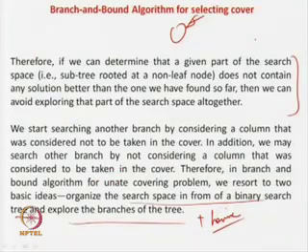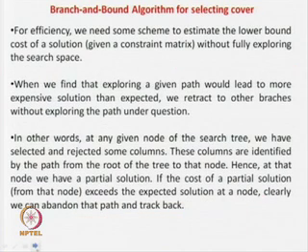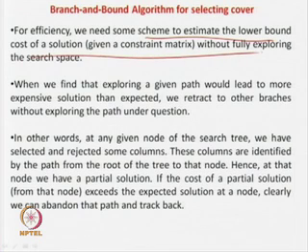So it is basically 3 parts: search space in the form of a binary tree, explore the paths. These are actually the branch and bound algorithm, and the complexity is very high. So you put the heuristic over here, and the heuristic will tell you which parts of the tree are not good to explore, so that you can branch and track back. Okay. So that means what? Now how do you start off with this algorithm? Okay. So what we do for efficiency, we need some scheme to estimate the lower bound of a solution without exploring the tree.